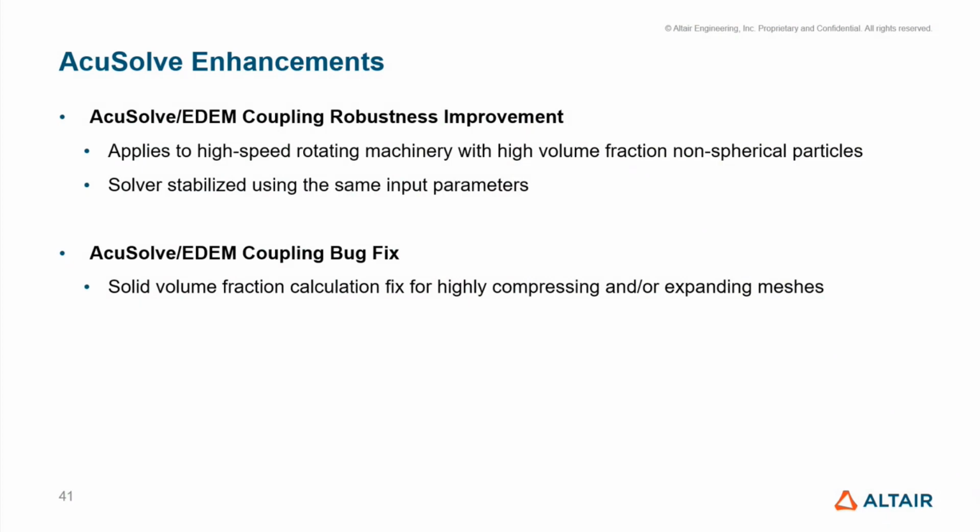Several improvements in addition to the main features have been added for version 2022 of AcuSolve. The first improvement is in handling high-speed rotating machinery in AcuSolve EDEM coupled simulations. The robustness of COSIM has been improved when large volume fraction non-spherical particles are involved. As a result, the solver stability has been improved without the need to add any additional parameters. And the larger time steps can likely be taken on the AcuSolve side as a result of this improvement.